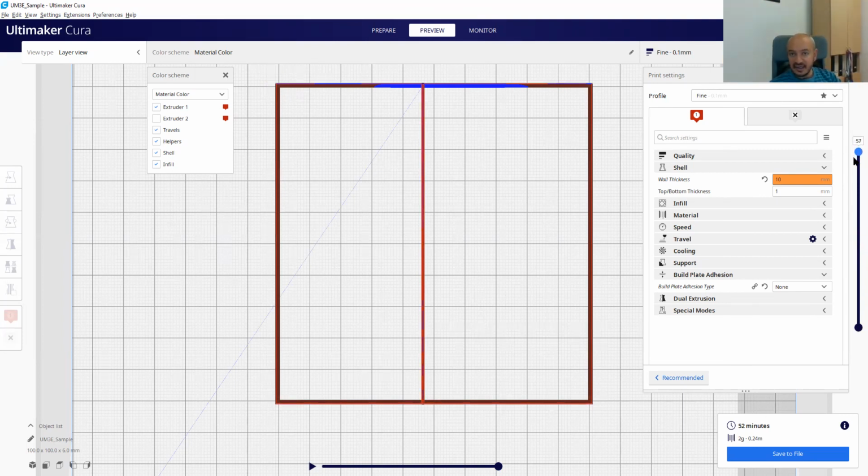And the thing about these fast travels is that, let me focus on here again. If you stop extrusion, then the material should be retracted. So during the printing, this white material is at the tip of the nozzle, it's depositing.